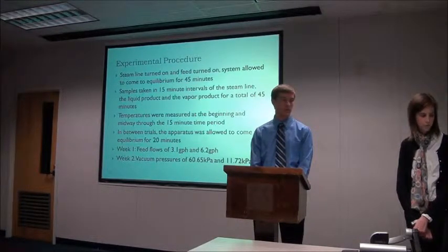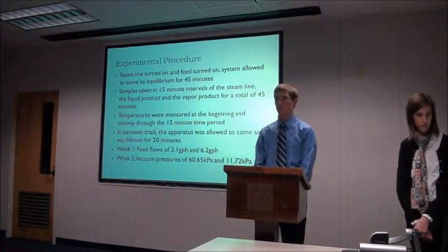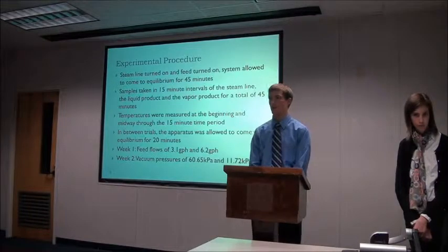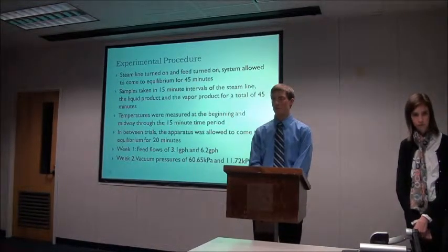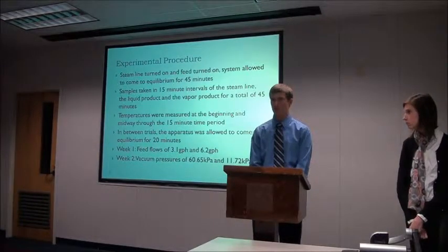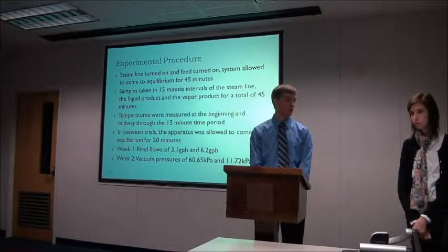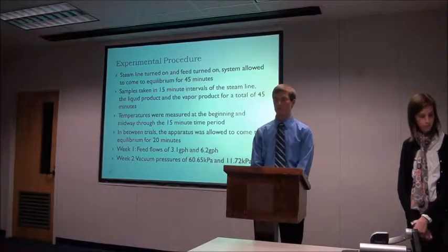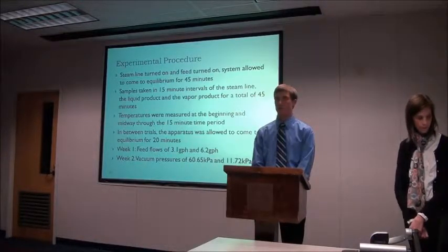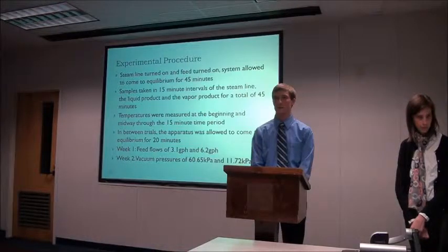After 45 minutes, we would calculate the feed flow or the overall material balance to make sure that we were actually getting what the flow meter read on the liquid stream, and then we would calculate the enthalpy change, the heat loss, and the capacity and the economy for the system.